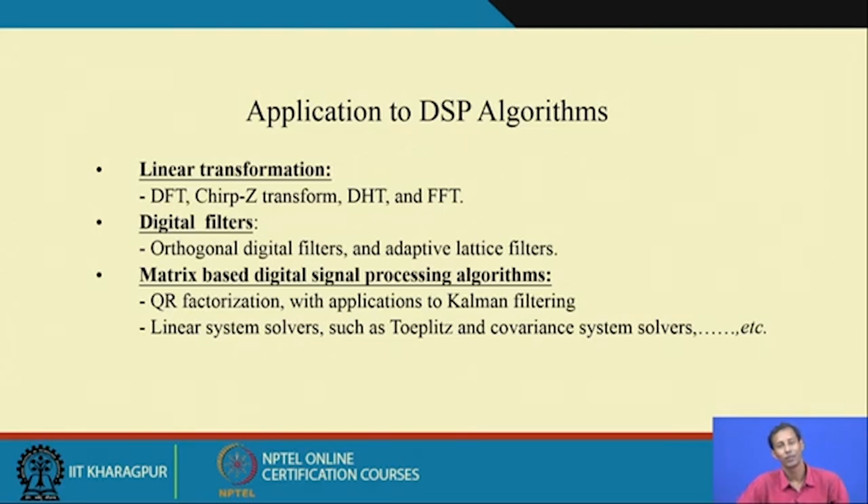We have noticed plenty of use of CORDIC for deriving the hardware architecture of functions like QR factorization, FFT, DHT, or DFT. This application area shows that CORDIC is used for various applications mainly in DSP algorithms. It is not specific to DSP; for wireless communication also we mostly use CORDIC.